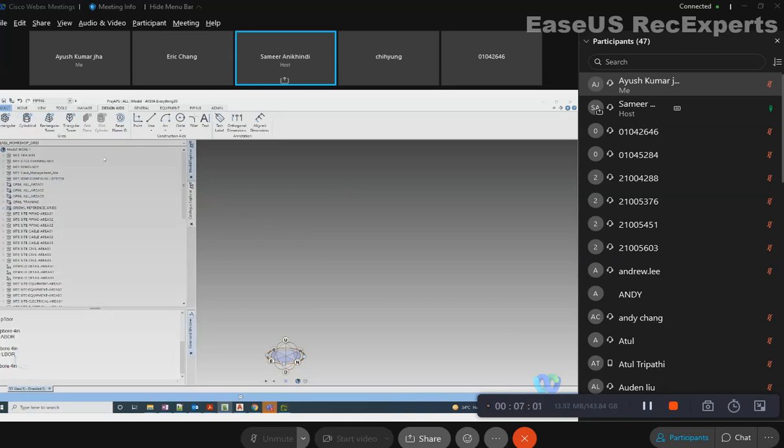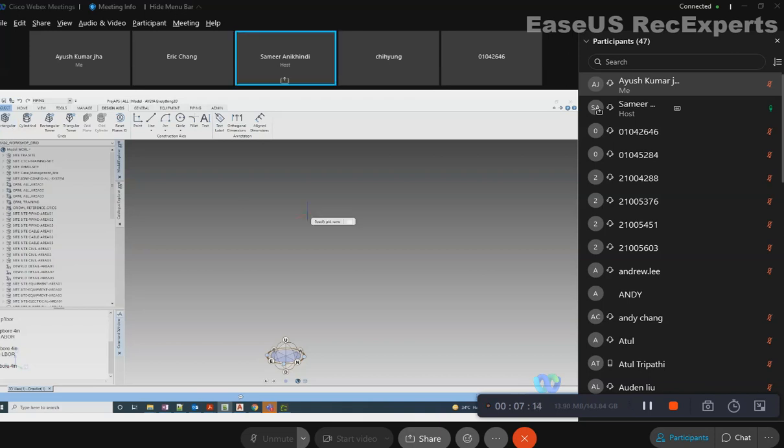So to make a new grid, what you have to do is click on the rectangular grid button. You can watch first and then I will give you 5 to 7 minutes to make it by yourself. So you can click on rectangular grid. It will ask you the name. To enter the name, the mouse might not be active, so just middle click anywhere. This is important. Just middle click anywhere and name it as CTCI area 01 dash grid. Don't give any space in the name. CTCI dash area 01 dash grid.